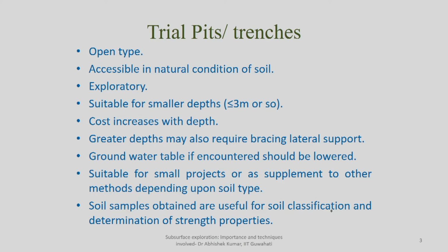You will get to know how the soil varies, because when you collect the soil sample and remove the soil from different depths, you will be able to see what kind of stratification is there, what the depth of vegetation is, visually by seeing the different colors. Even by touch you can get an idea about whether the soil is clayey, cohesionless and so forth. So, it is like an exploratory method; even without going for detailed investigation by means of in situ or laboratory tests, you will get